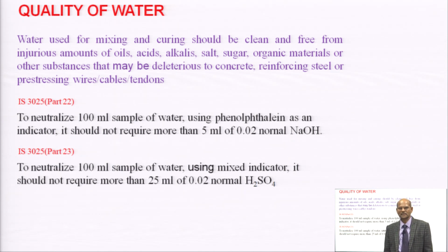Suppose there is chloride or sulphate in the concrete. Chloride, what will happen? This chloride is going to create corrosion in the reinforcement, and the life of the structure, the durability, will get affected. And similarly, if the sulphate is more, that is also going to cause expansion, and finally reinforcement will get affected.